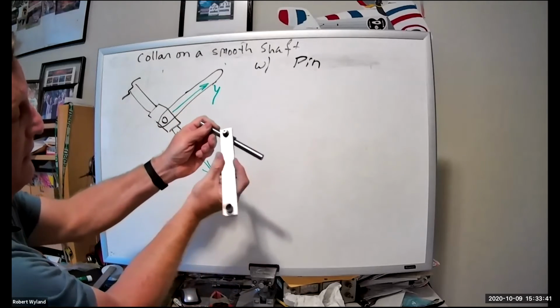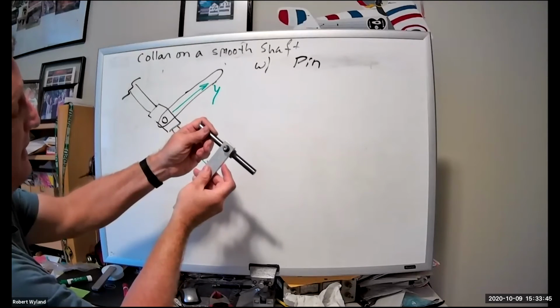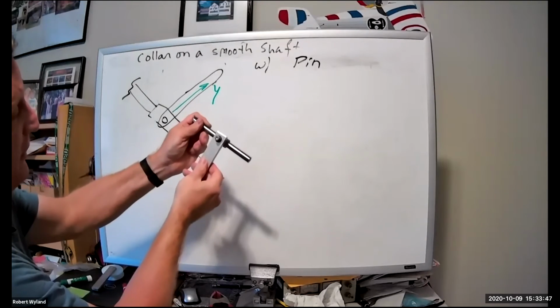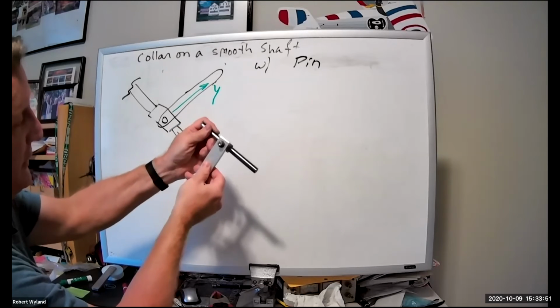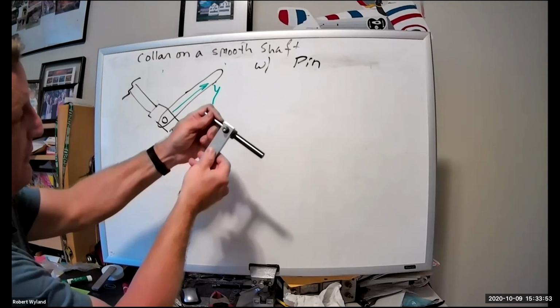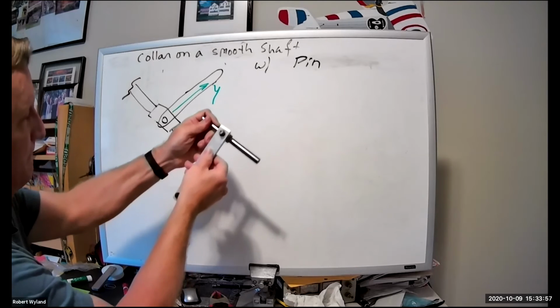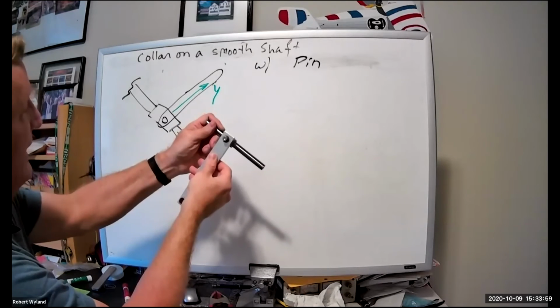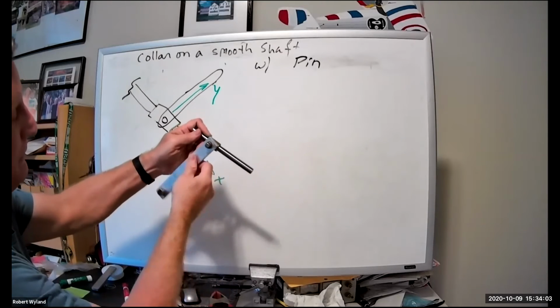Or I could do it upside down like this, so you might be able to see it better. There's nothing happening. Now in the Y, if I push or pull perpendicular to the shaft, I get a reaction. It's resisting me. It's not allowing me to do it. I'm getting a force pushing back on my force. And if I try and rotate about Z, it rotates freely.